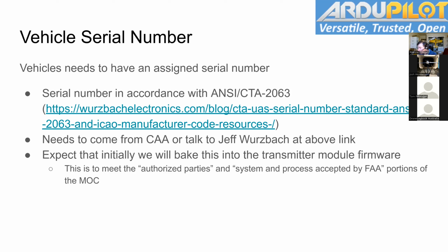So if you're planning on shipping your vehicle with multiple GPS options and they're not compatible as far as the GPS type is concerned, for example, you're offering customers either Septentrio GPSs on UART or serial u-blox on UART, yes, you would have to have two firmwares to support that. If, however, they're both DroneCAN-compatible GPSs, so they're both using AP_Periph, for example, that's just the one parameter. You set the GPS type to DroneCAN and you're done. Now, there are changes that are needed.